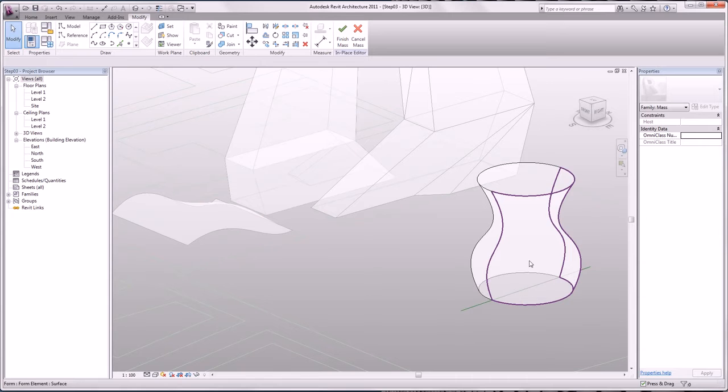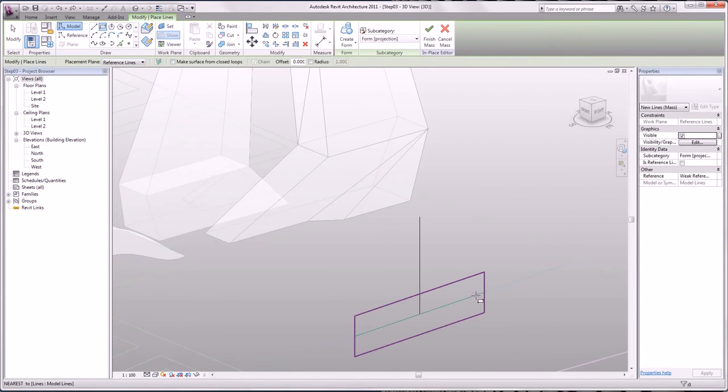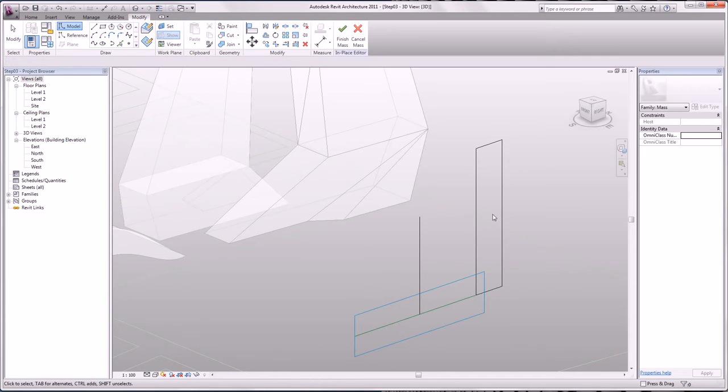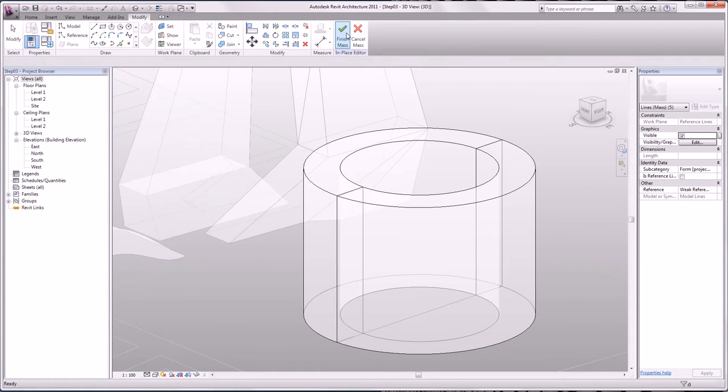Select it. We use the Ctrl+Z shortcut to undo our changes. Now we draw a rectangle. Height of about 45 meters. We select now our middle axis, the rectangle. Click on Create Form. Now we have generated a tube.